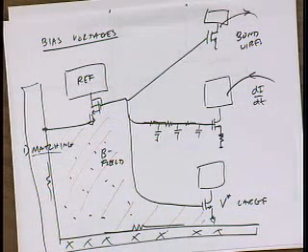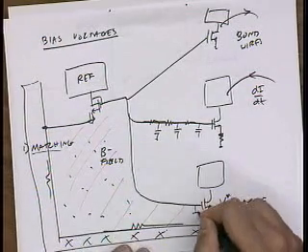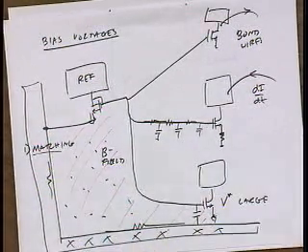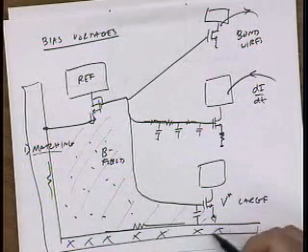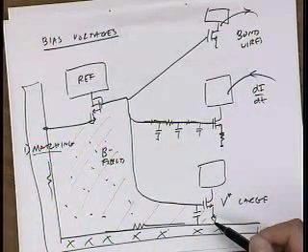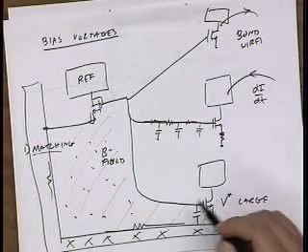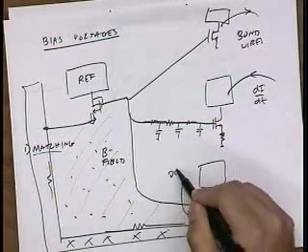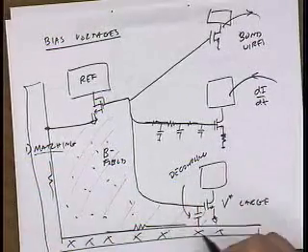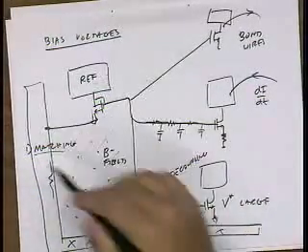Okay, Lee? Put a capacitor to ground? Yeah, it's a good idea, right? If I put a capacitor from here to here, this will work, but unfortunately this only works at high frequency, right? So at really high frequency it's beautiful. It does a great job. This is called the decoupling cap, because it decouples your bias circuit from all this stuff.